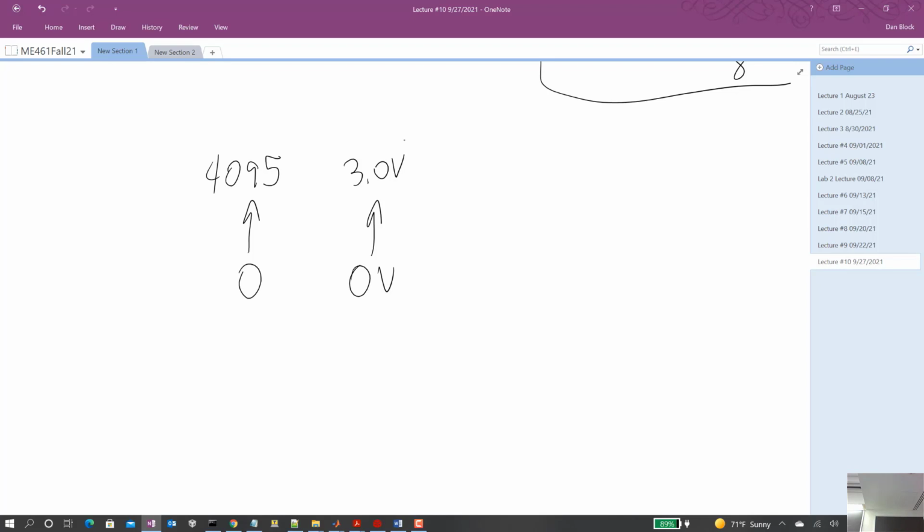There's other DACs out there. Some of my stuff I use in the labs over in ECE for other classes, my DACs over there range from minus 10 volts to 10 volts. So you can get different voltage ranges. Really all it is is a bunch of op-amp circuits inside. How much do you guys remember about op-amps? So the DAC actually is an op-amp circuit.